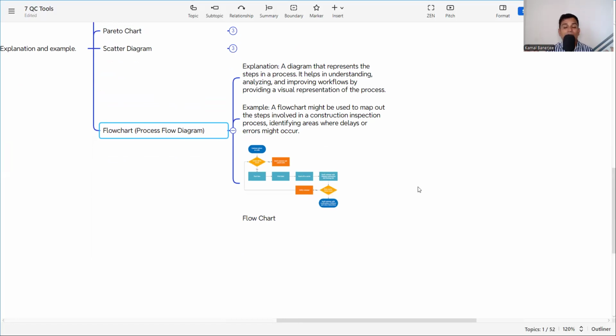First, the worker or the engineer has to do the work. Then the engineer has to check, and if satisfied, they will issue to the internal quality team that my work is ready. Then the internal quality team will check, and if they also say okay, then it has to be raised to the concerned authority, maybe the consultant, the project management consultant, or the client, and then they will come and check, and if it is okay, they will say go ahead and proceed.